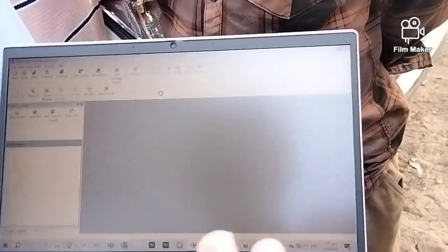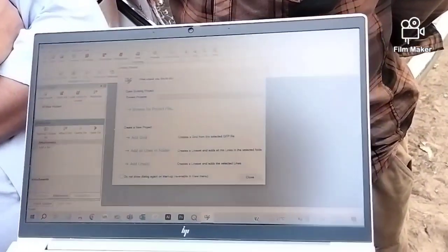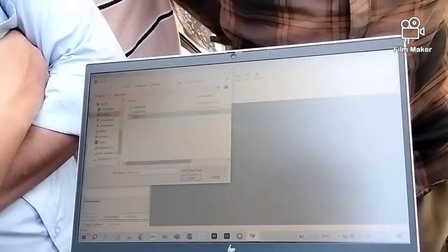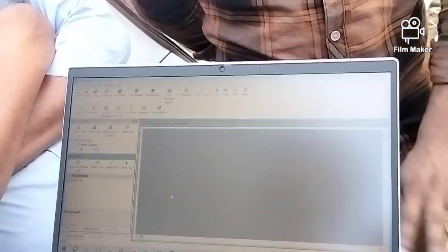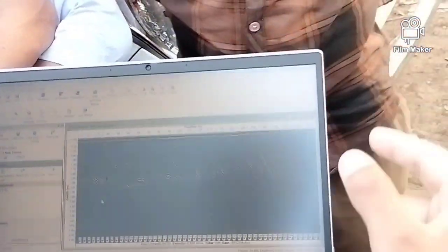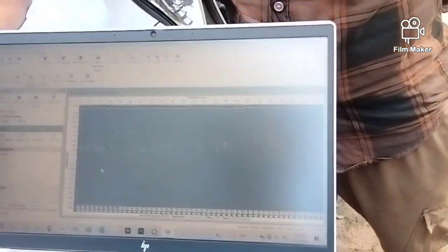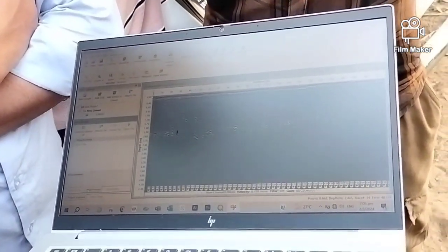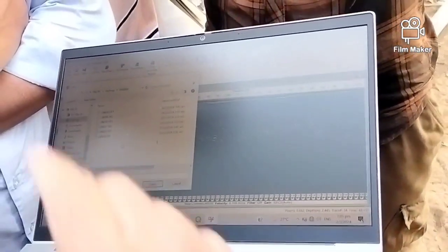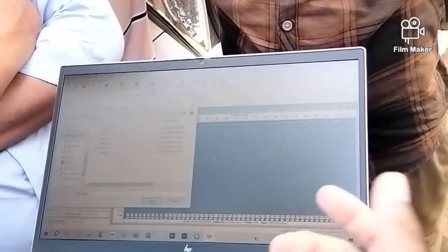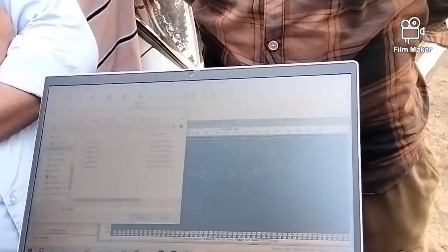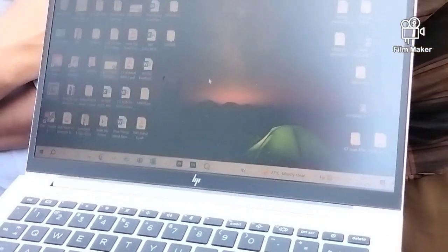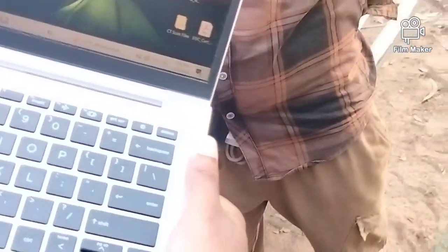It's taking some time. Okay, add line, just add some line. In the GPR machine, is there no option for the elevation level? No, because GPR always sees the two-way travel time. It never says if you are going down or going up. So you need to have GPS attached to GPR. If you go here, attachment, you can just add a file, which will be .top, for topography. And then once you attach it, you can see the topography. Okay, we are getting the distance also, but it is wrong, right? What, the distance? Elevation is not showing. Distance is also